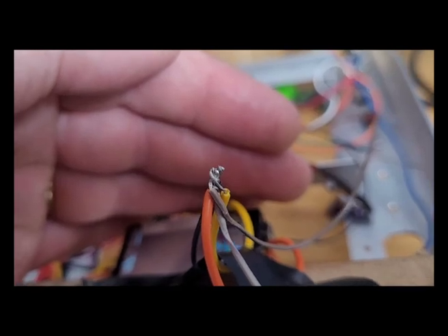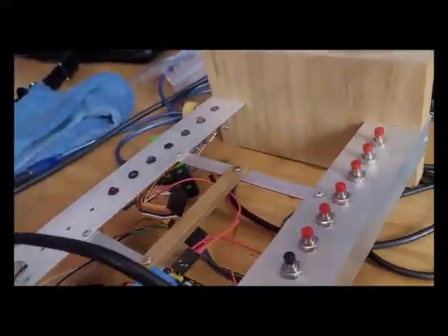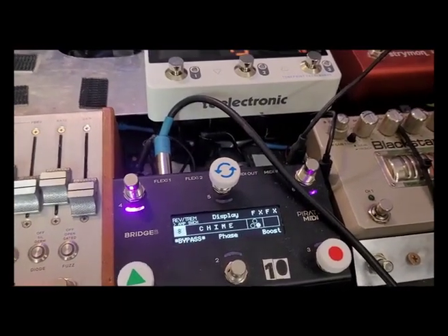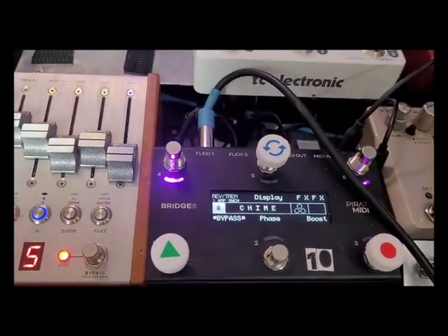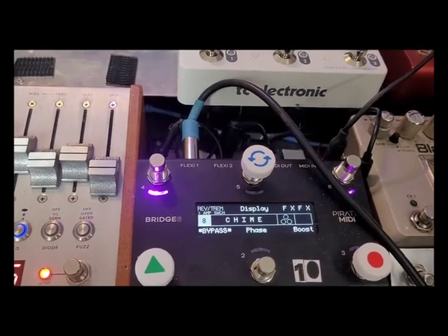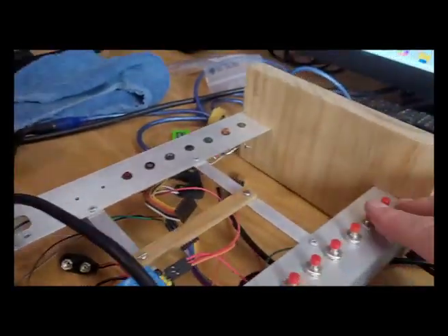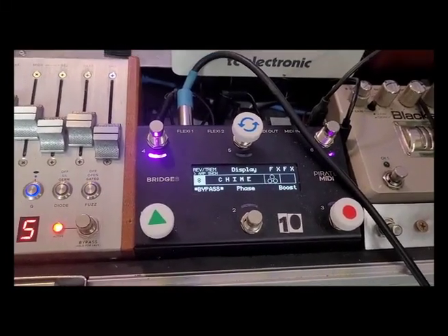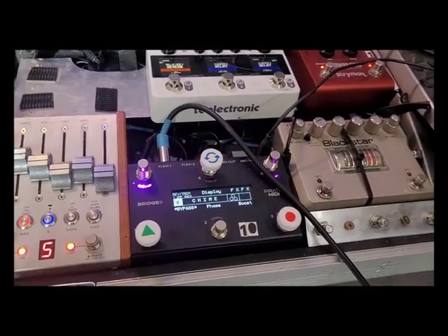So all the wires, tip, ring, sleeve, are connected together, and you can imagine what the results are going to be when I start operating the switches. It only wants to switch tip and ring. I can't make it switch, so I'm operating all three. I'm cycling through operating all three switches here, and the only thing it'll do is that one switch. It doesn't like it. This is why we need the diodes to isolate the switch state of tip and ring. So I'm going to get those diodes now and show how that can be fixed.